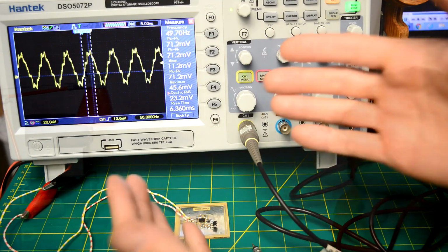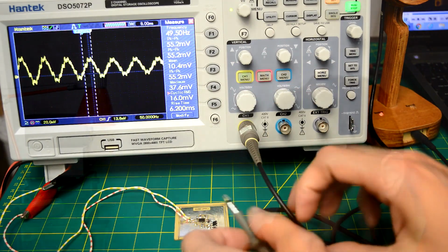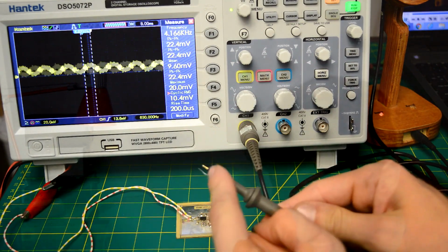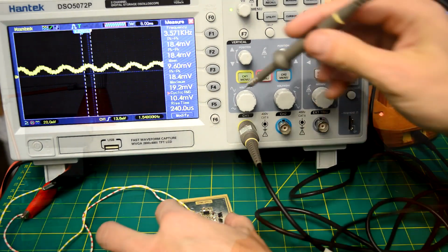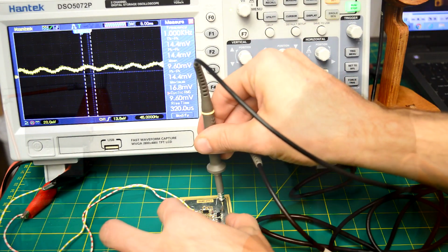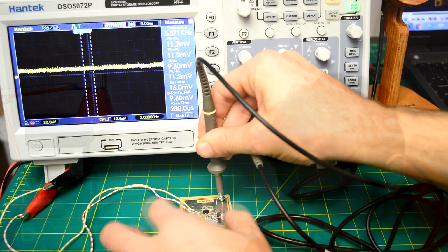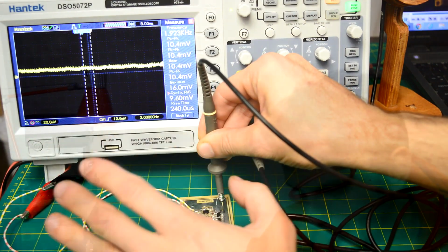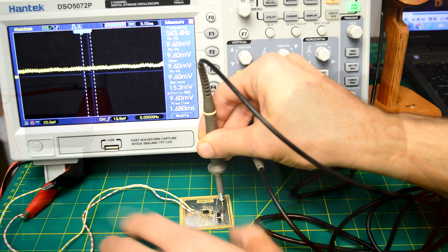Now, what do you think this circuit will behave like in real life? Will it be the same or will it look slightly different? Let's just see. So here I got my circuit. I got my probe with a low noise connection, so very short lines. If I look at the ground only, we can see the noise of the ground and of the oscilloscope. So anything that's above this is actually generated by the circuit.